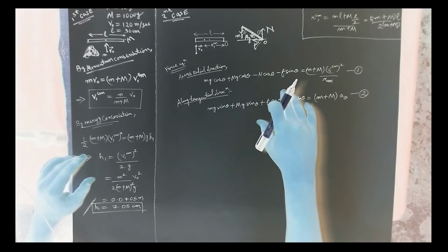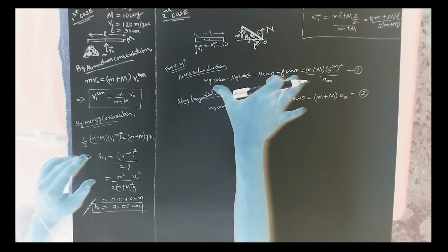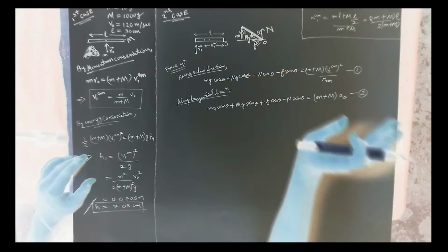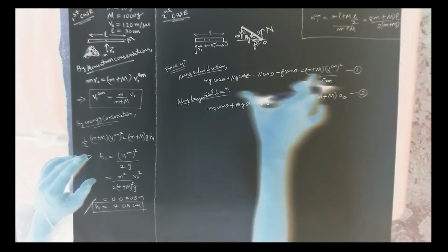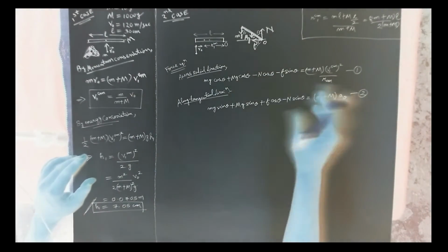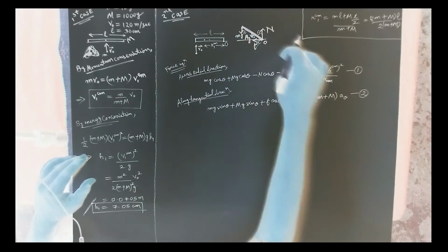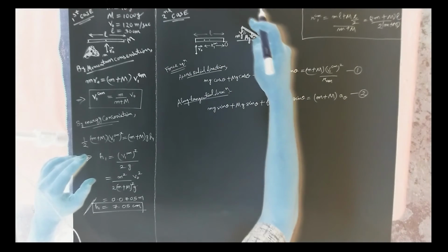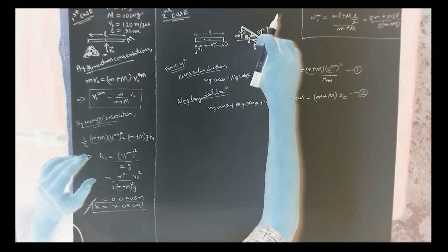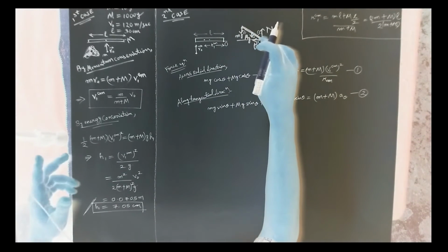Or in other words, we can say these forces become less than this value, as the N, f and theta values are varying. This will make this one less than this thing, and vice versa. So this is going to lose contact along the radial direction. The centrifugal force will be greater than all the forces acting in the radial direction. So this will lose contact, as we have seen in the video also.